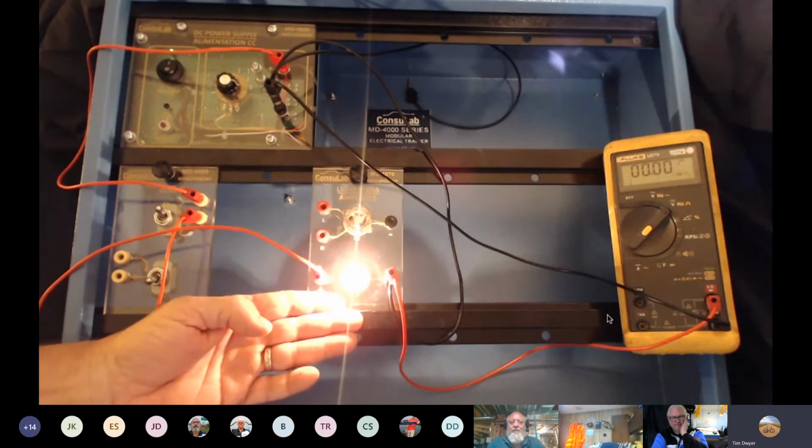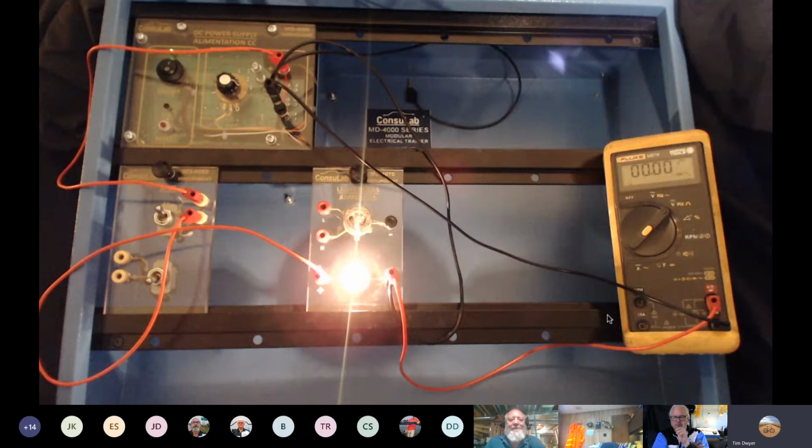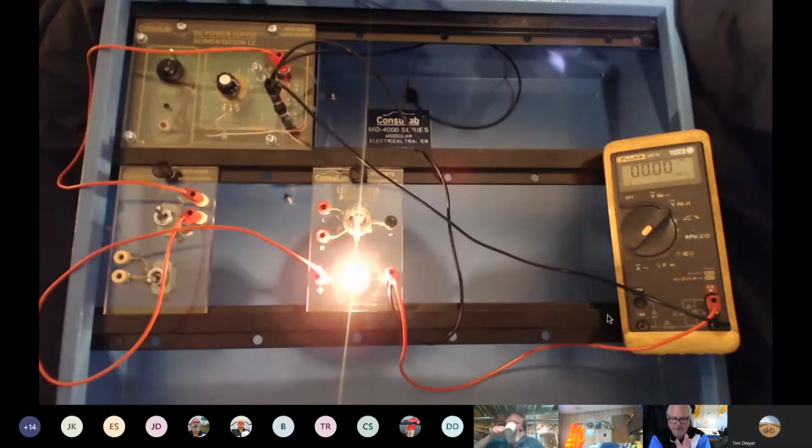This tells me there's current flow. My eyes tell me that. I can put a meter on there, but eventually you're going to figure out whether it's performing correctly or not. There's current flow. So what I'm asking the student to do is to be so discerning that they eventually learn to go up and range the meter, because zero, if there's current flow, it's not possible.